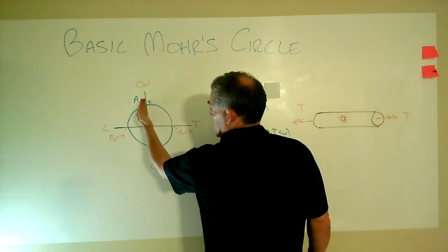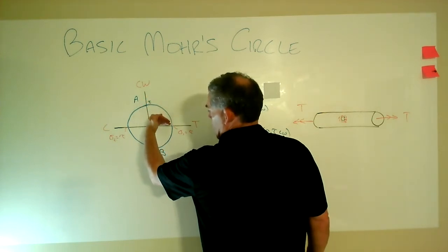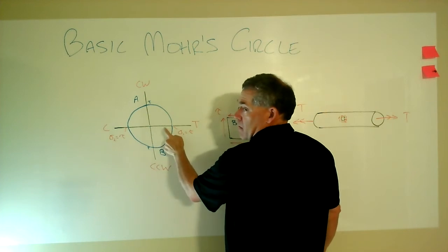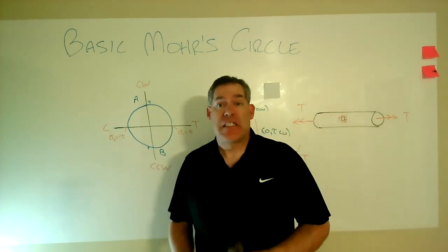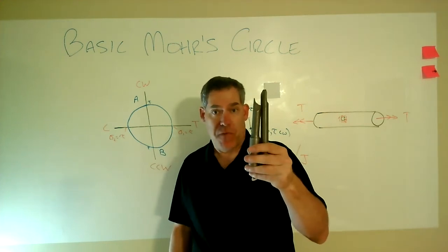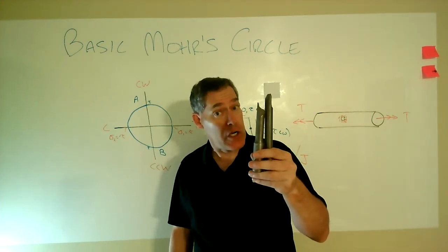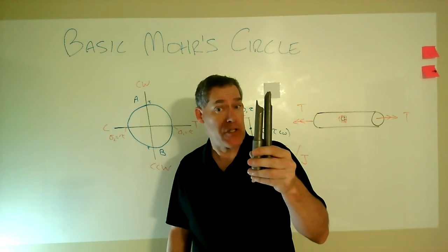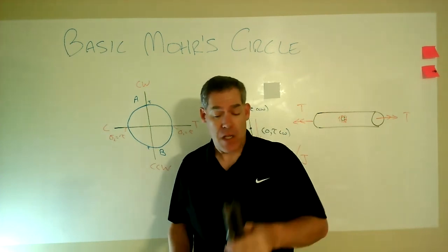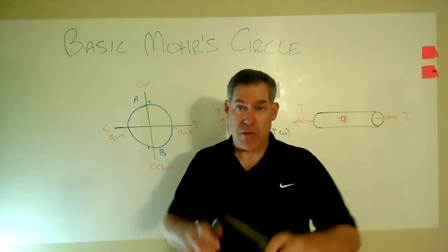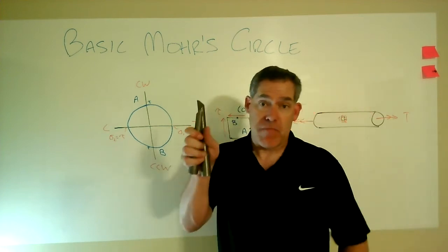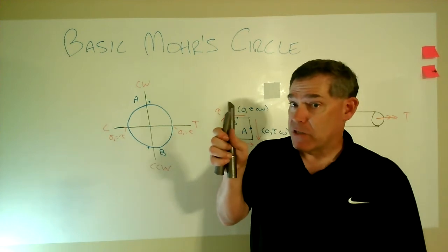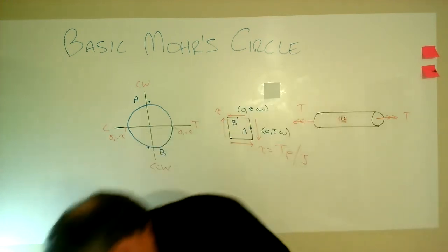So 90 degrees from the cross-sectional plane, right there, is the maximum tensile stress. Ductile metals will fail in shear, not in tension initially. And this thing failed in tension without a doubt with that little wrap. This material, even though it's steel and it's metal, is not ductile. This is actually a brittle material.